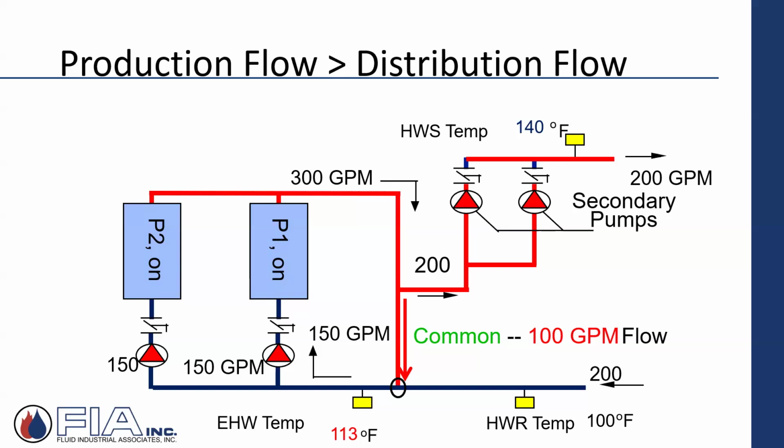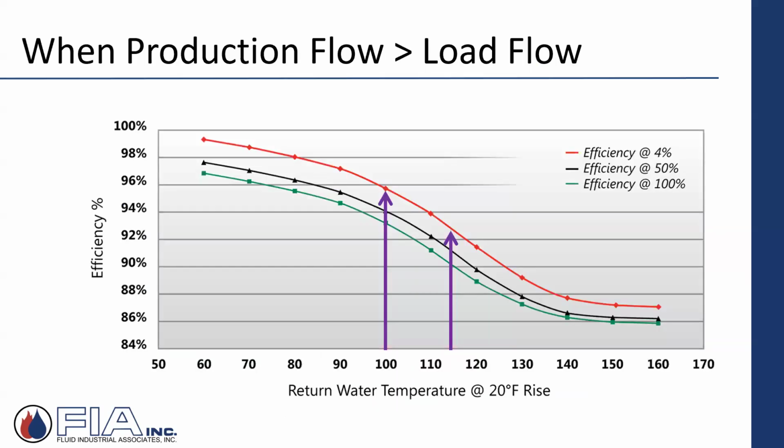So the whole little exercise here is just to lead up to saying, if I can keep this water as cold as possible, I really can influence the efficiency of the boilers, the firing of the boilers over the course of a day, a week, a heating season, five seasons, add it all up.